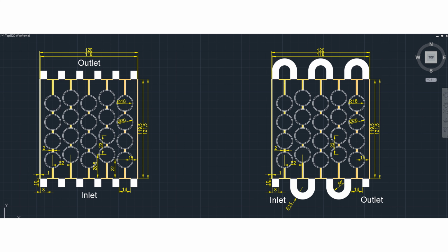Okay, so first of all I will just create the outer portion, that is this one, 119.5. I am avoiding the outer casing because ultimately it will add to the number of nodes and elements. So for simplicity I am just avoiding the outer casing over here. So 119.5 is the dimension that we are going to follow. So let's create the geometry with the help of the design modeler tool. So go here. I will create a primitive.